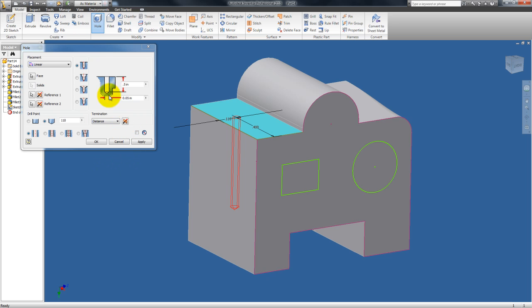Next thing to know is these types. So we can either have a drilled hole, a counterbore, a spot face, or a countersink. Let's make it a countersink. Now we can pick all the dimensions here. So the angle, let's keep the angle the same, but the diameter of the countersink, let's go 0.2. Actually 0.1.